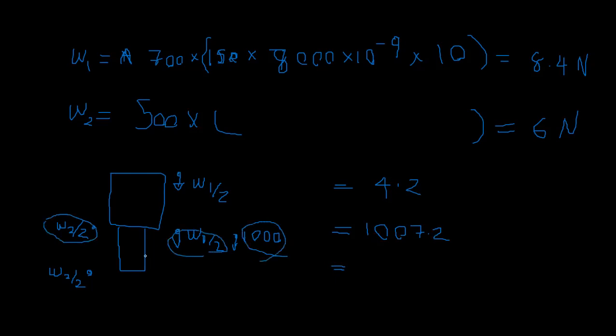So you have to add each. So what we did was, the external forces are exactly at that point. The other self weights are not acting at this point. So you need to make sure those are captured within these nodes, because we are solving the equation at these nodes, right? So the weight taken by that part is there, the weight taken by that part is here. And this part is also counted to 2. This part is also counted to 2.